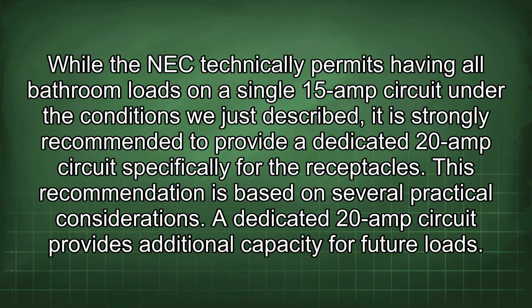While the NEC technically permits having all bathroom loads on a single 15-amp circuit under the conditions we just described, it is strongly recommended to provide a dedicated 20-amp circuit specifically for the receptacles.